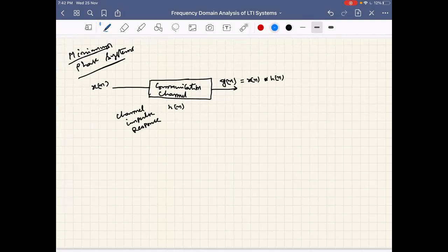But for many practical purposes, what I wish to get is not the degraded signal after the communication channel. I would like to put in a virtual system, which I am calling the inverse system, that mitigates the effect of the channel. Why? Because I want x[n] here, the exact information. This is modeled as h_i[n], to have x[n] back from y[n].